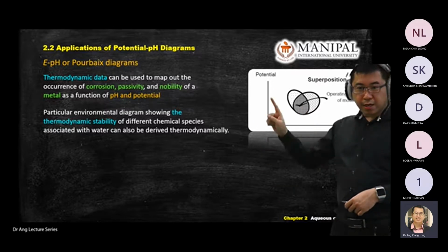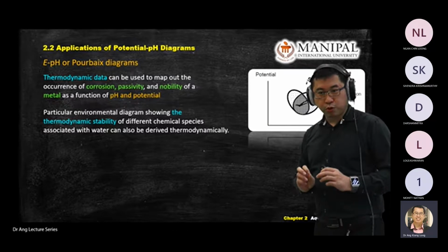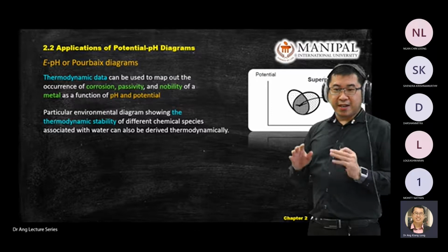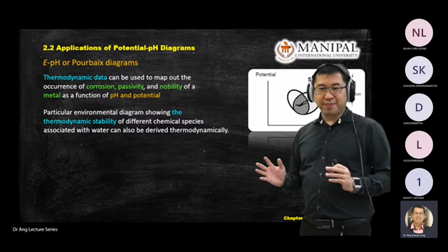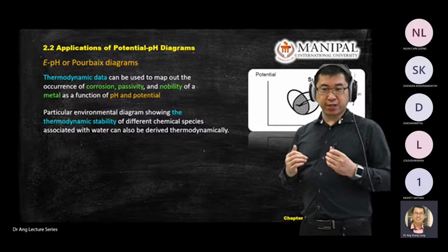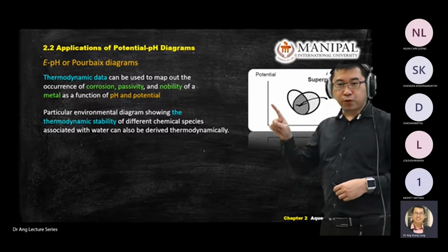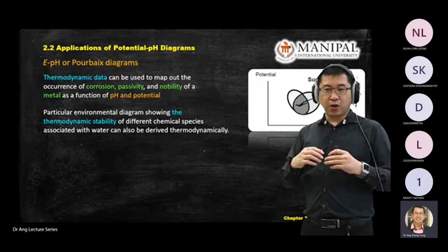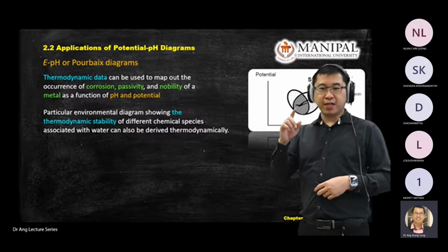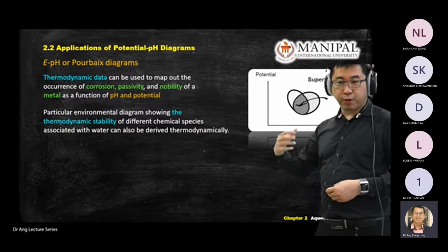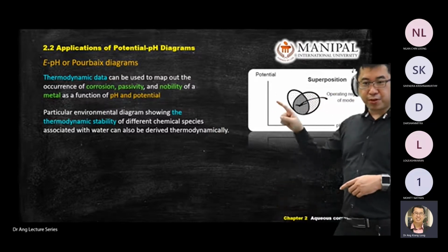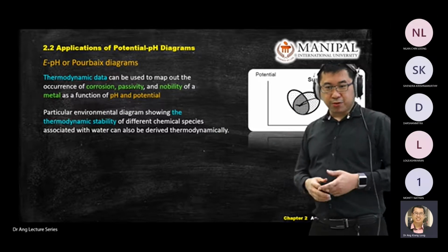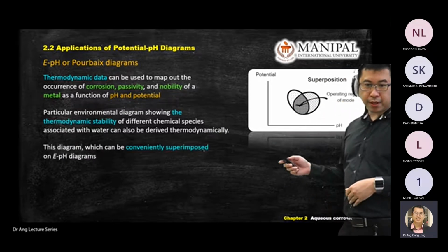Again, potential here is because of the corrosion process, and it is not an external supply of electricity. Again, corrosion and electrolysis are different. Corrosion happens without external electricity. So the voltage or any electricity properties that you measure here, it generates on the surface itself through the exchange of electrons, that we covered previously. Okay, so just take note of this. Don't mix up with the electrolysis process.